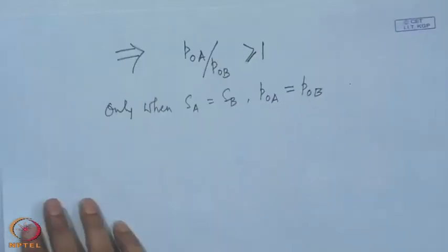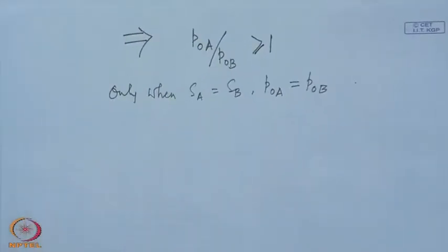For a stagnation condition to exist, it is not enough that the flow is brought to rest. It must be remembered that the flow must be brought to rest adiabatically for enthalpy and temperature, but isentropically for pressure. That is, the equilibrium condition must always be maintained while the flow is imagined to be brought to rest.